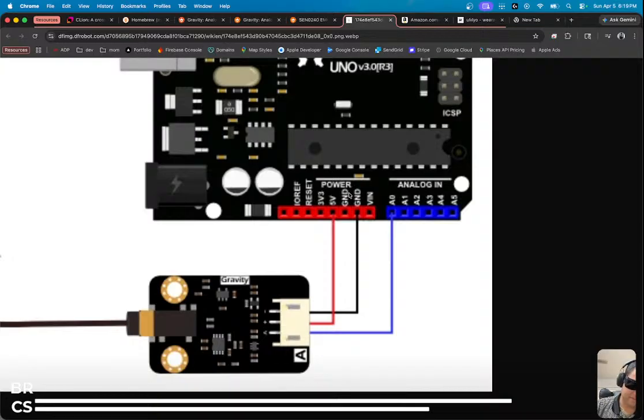So technically I'm done. I should be able to connect the ESP32, assuming this is right. I'm gonna double check it. 3 volt to the rail, then red to red. Blue is the data, goes to D2. Black is ground, goes to ground. Ground is connected to the ground pin on the board, and then the rest of the thingy is connected. There you go. Okay, looking good.